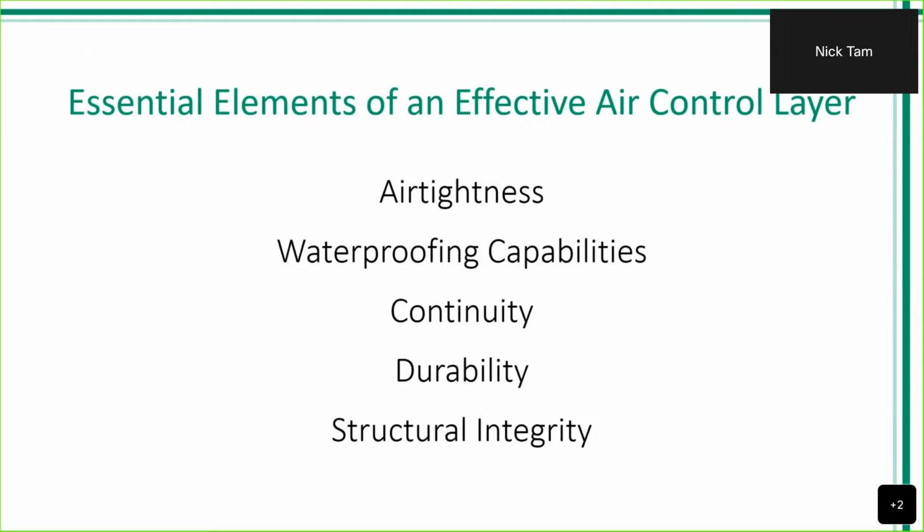And for structural integrity, our buildings move, right? We're always going to have something that alters the way the building contracts and expands. With any structure material that we use to protect our building from moisture or air, we want to make sure that it can also expand and contract with the structure, as well as have good recovery.